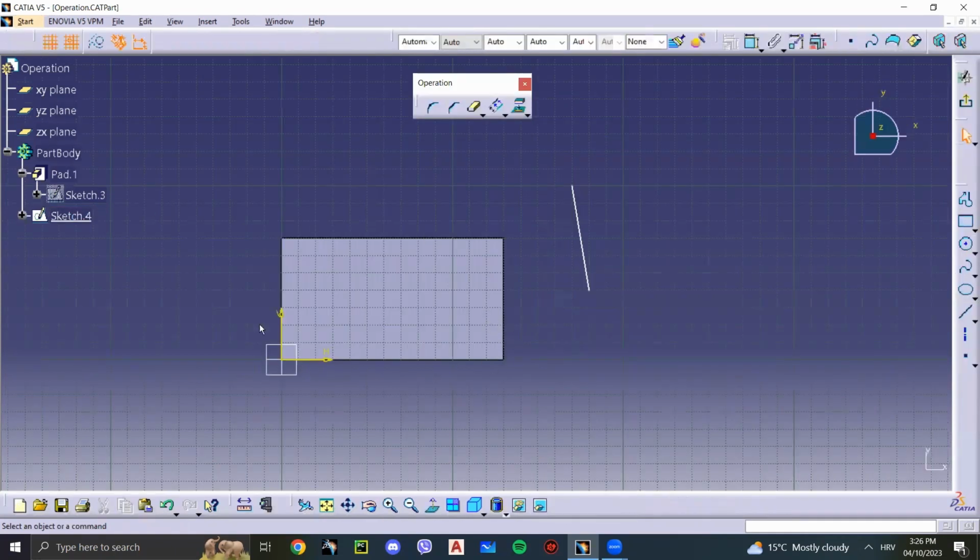Let's say you want this here to be copied. You can select it all and project 3D elements. And now if we deselect it, we see that we got yellow lines. These are projection lines. Now the problem with these lines right now is that we cannot move them around. We cannot really do much with them. We're just using them as reference.